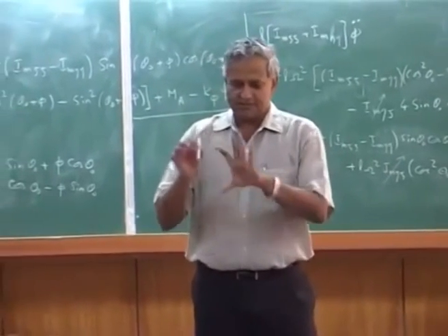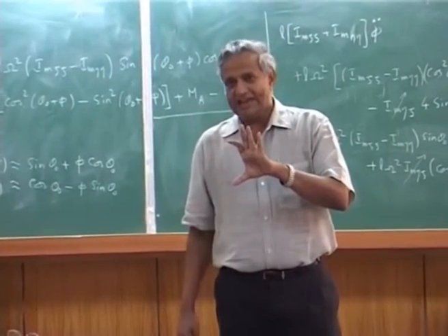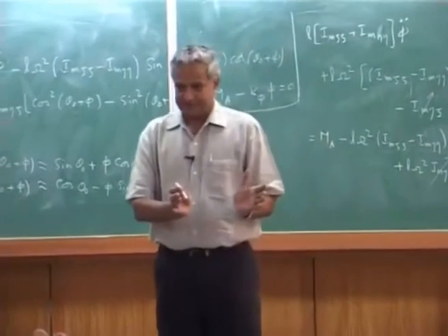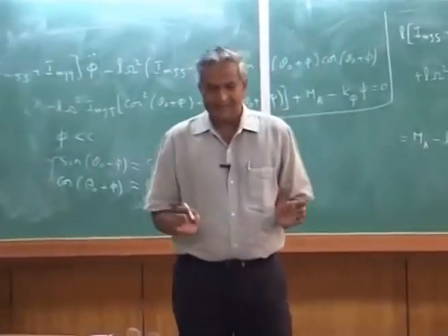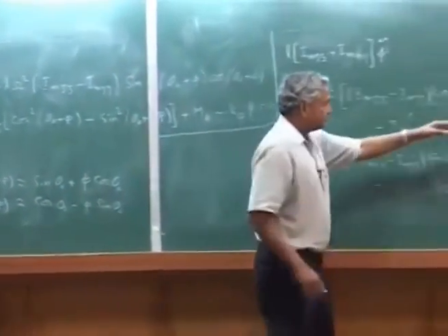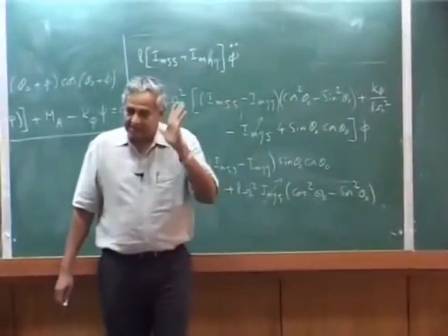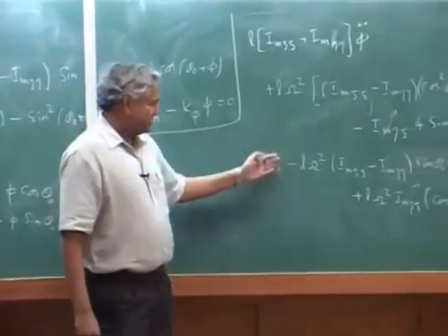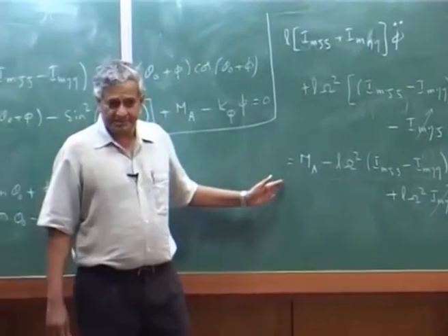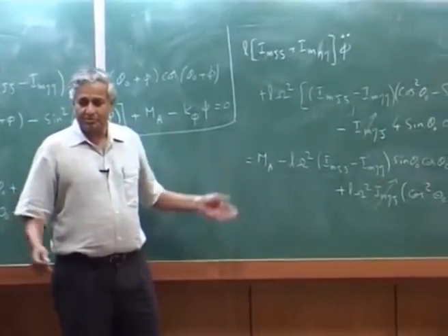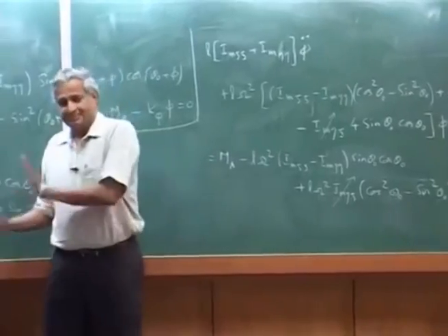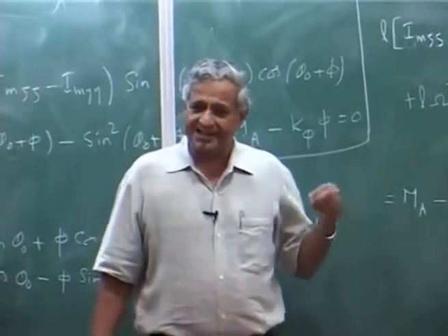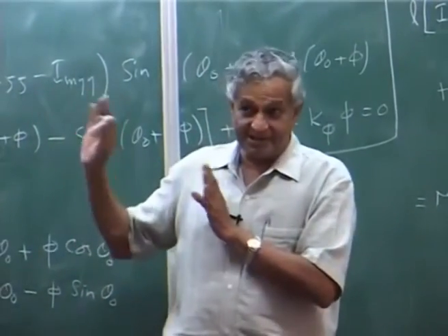Usually, of course, control rods are very small, so they are given by EA over L. But the swash plate will have its own stiffness. Nothing is rigid. So that will give this. There will be a loss in pitch angle. Now I will not write any expression for M_A, because this is basically the aerodynamic load. You can use a quasi-steady aerodynamic load or a very simple instantaneous angle of attack, take it and put it. They are quasi-static. These are terminologies in aeroelastic analysis.